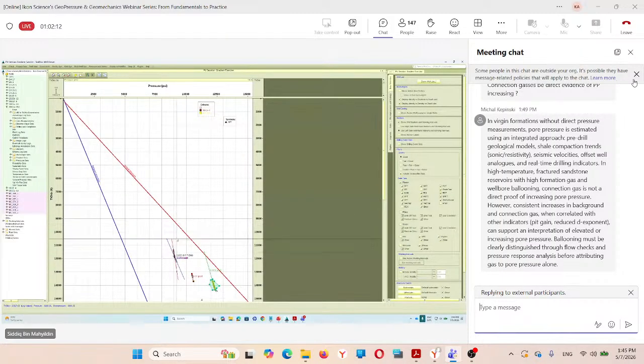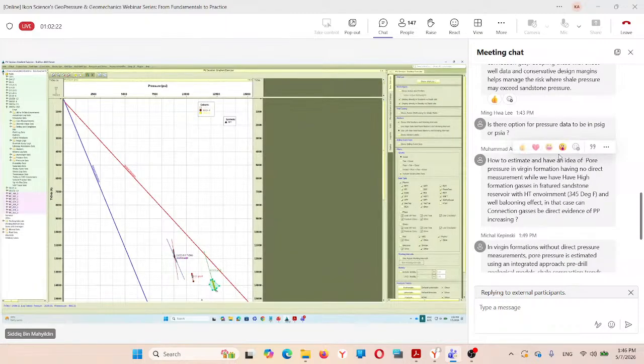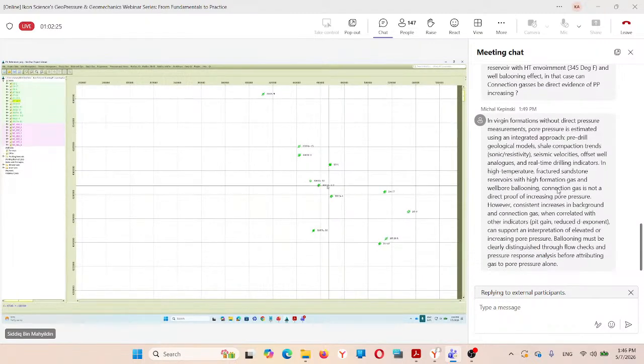We can easily see that this is one system, this is another system, and this is another pressure system. So all these three wells, although they look quite close to one another in this area, one is here, one is here, and one is here, they all have their own pressure isolation. So they are not connected to one another. Imagine that you are drilling a well in between, maybe somewhere over here. Then you need to question yourself again: will this pressure measurement data be better represented by this well, the well over here, or none of them, because it's a totally isolated system, right?